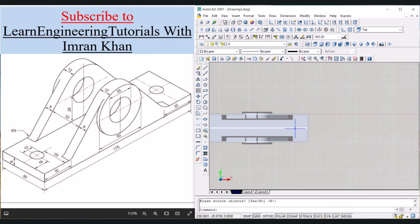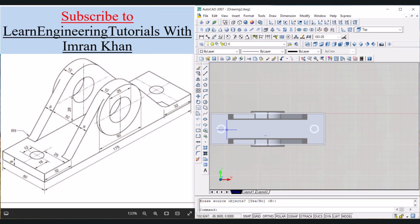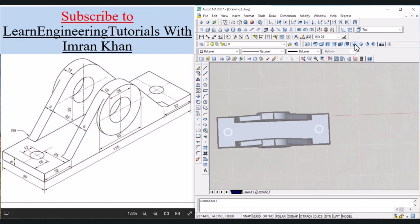Now we want to mirror this object, so click on top view, select this circle, click on mirror icon, select this point, then this point, erase source object no, press enter. So both these objects have been mirrored. Now click on southwest isometric view.